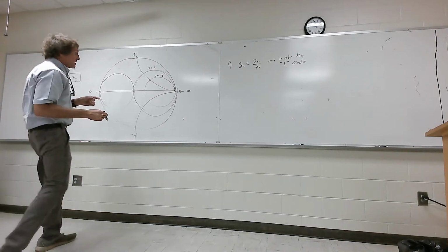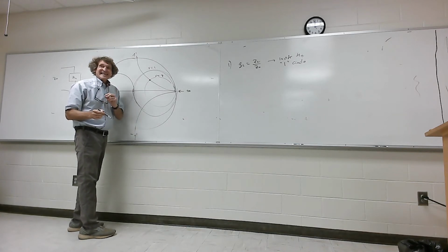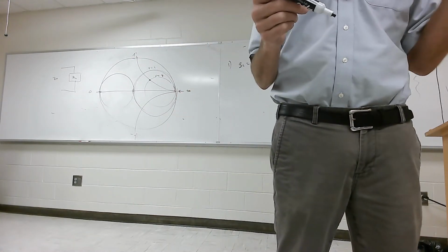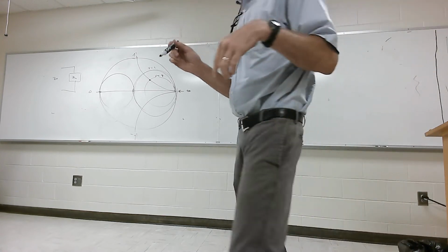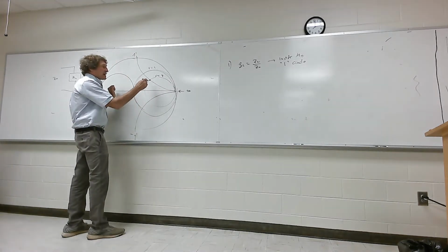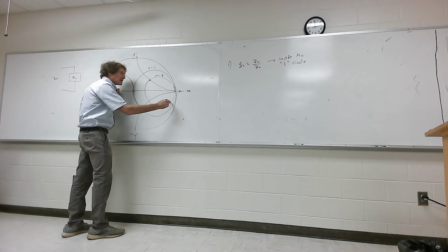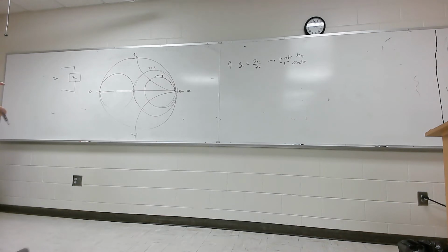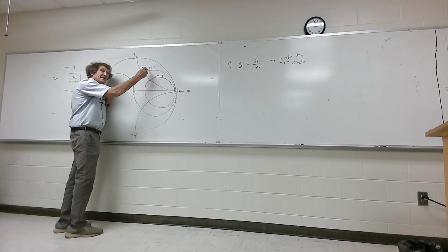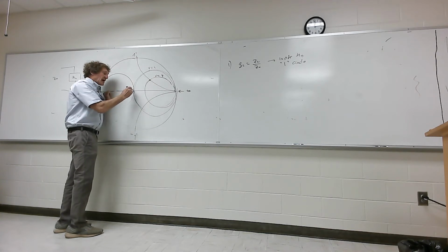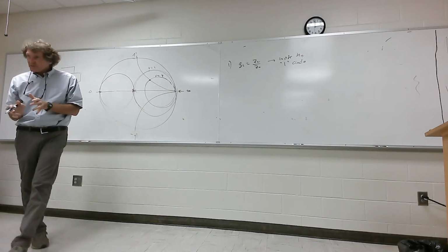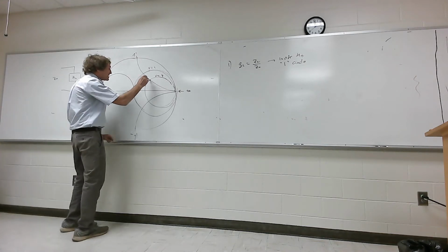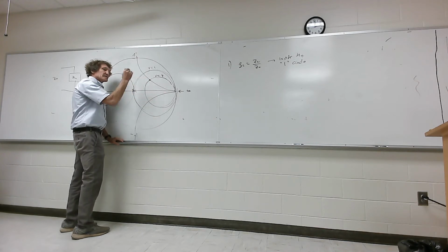It's somewhere in here. Now, when I do impedance matching, what I'm going to be doing is adding elements that don't waste power. I'm either going to add capacitors or inductors, and they have values of jX or minus jX as far as their impedances. What that means is, if you think about this, I can add or subtract j and move anywhere around this circle. You all see that? By adding it in series, I can be anywhere on that circle, but I can't get to this circle. That's where I want to go, because then I get rid of the actual impedance. This is the point. We want to go right to the center, because the reflection coefficient is 0. You all follow me on that? That's the goal. So, if we're inside the one circle, no matter what we add in series, we can't get to this circle. You all follow me?